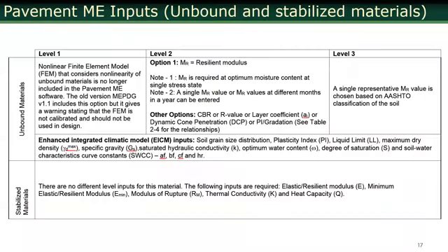Outputs are not sensitive. How about unbound materials, soils, subgrade, and so level 1 input for unbound. Originally, when they were coming up with PavementME, they were thinking of a nonlinear finite element that considers nonlinearity of the base layer. Unfortunately, they decided to give up, so they did not include finite element to include the nonlinearity of the base. What is nonlinear? When I say nonlinearity of the base, this is what I mean.